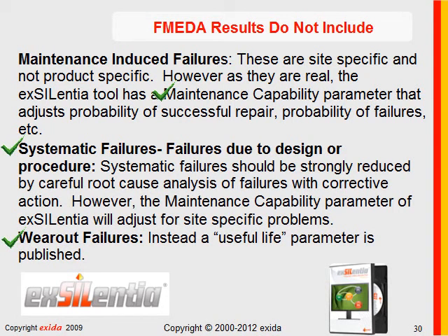Instead, FMEDAs produce a useful life parameter, which is the time period for which the failure rate data is good, and the intent, as specified in functional safety standards, is when a product reaches its end of useful life, you need to replace it or refurbish it.